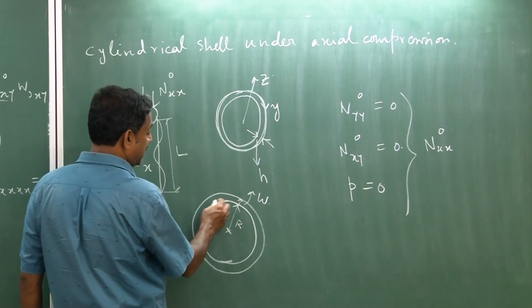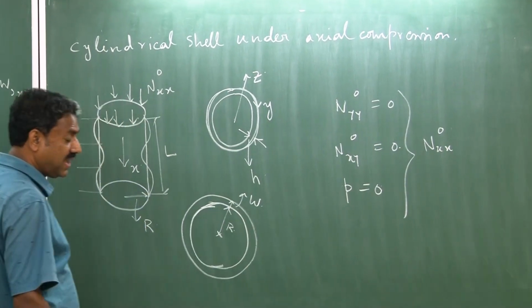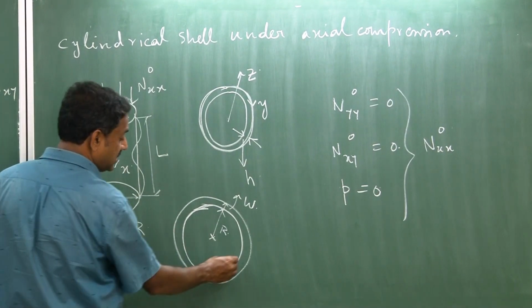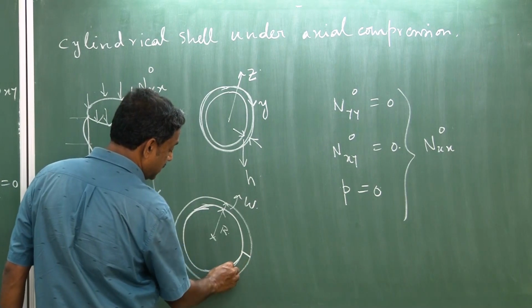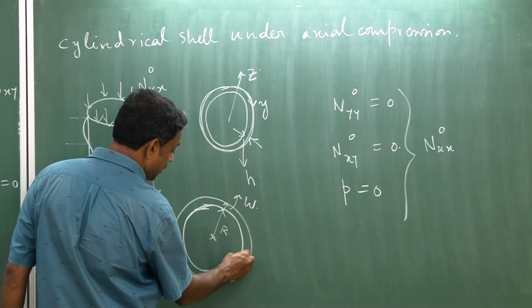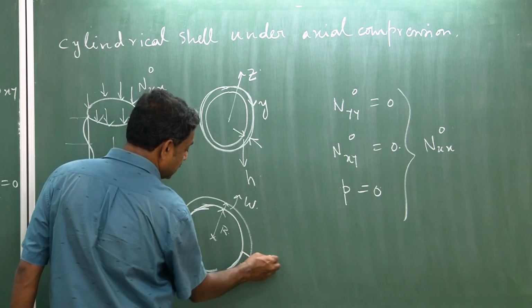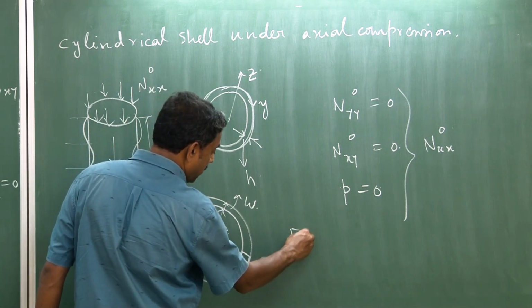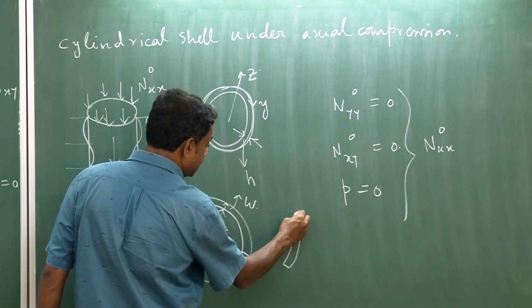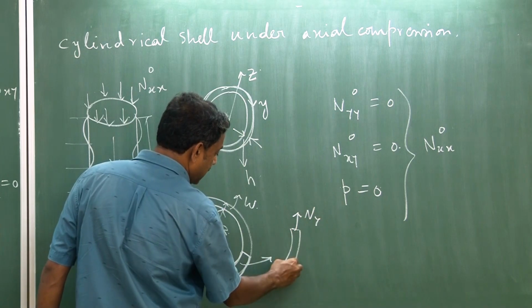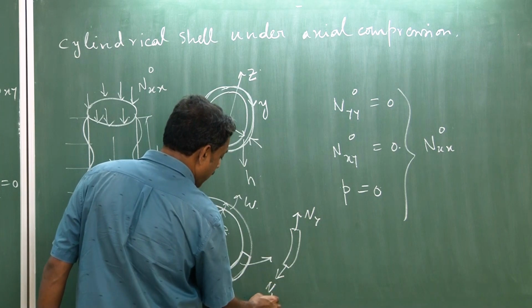Because of the axisymmetric assumption, it is just expanding, and that allowed us to take a small section and write down that governing fourth order equation. Then we considered the equilibrium of a small element, and that's what we solved for the axisymmetric case.